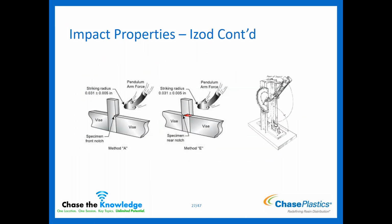So if you're looking at the part again, this is the overall test apparatus. Some of them are a lot bigger and a little more complicated now, but it gives you an idea. Here's your pendulum up here with the hammer. It comes down, and then you'll see the part standing up right here. When it drops, it hits it, and then it takes the energy that was required to break that. And so if you're looking directly at the part itself, it's being held, the pendulum comes down, hits it, gives you the value. So that's for your IZOD.